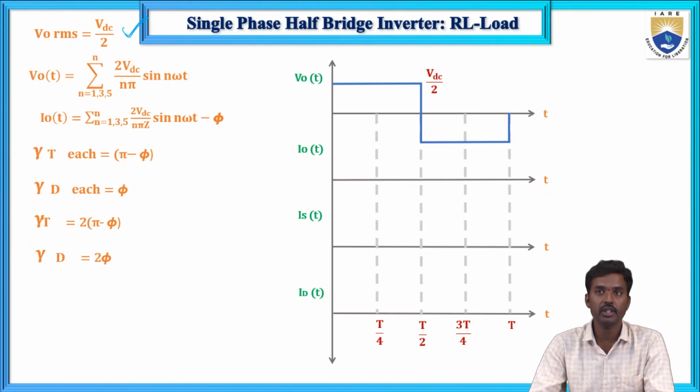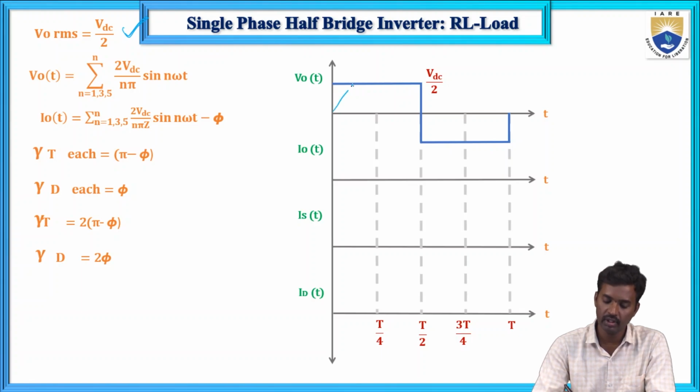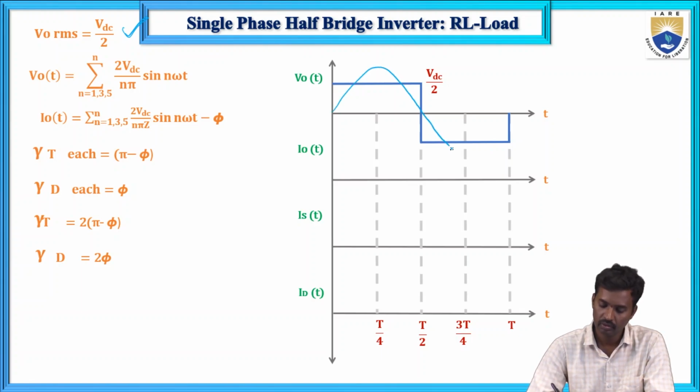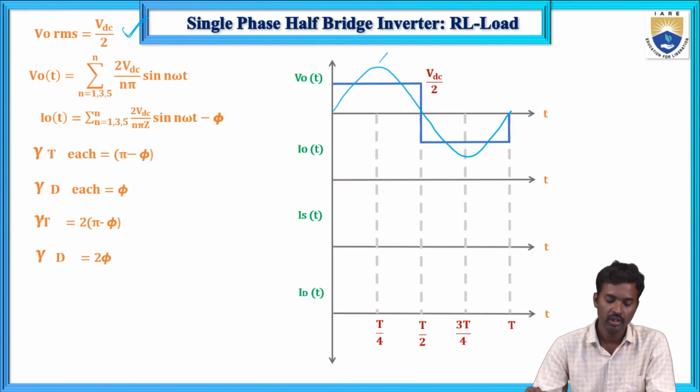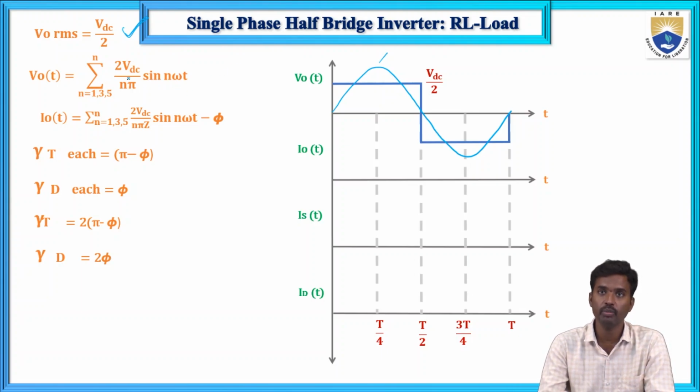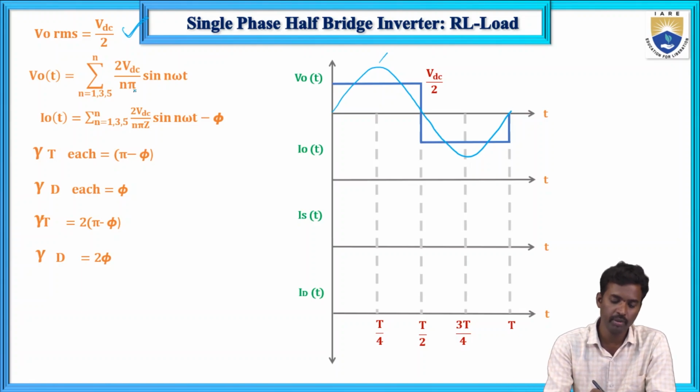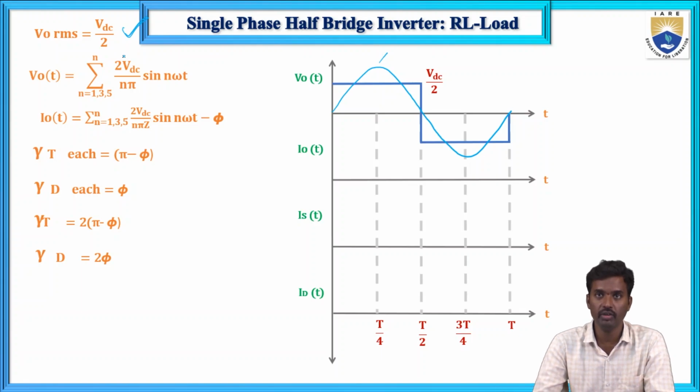in the Fourier series. So this voltage is always the peak value of the fundamental. So this is the Fourier series of output voltage, n equals 1, 3, 5 summation, and now here 2 VDC by, actually this is 4 Vs by n pi sin omega nt, but here Vs equals VDC by 2, that means 2 VDC. So that we already discussed.